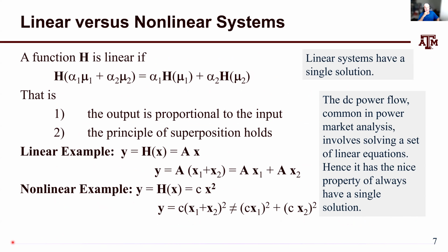Okay, we're going to be talking about nonlinear systems today. The power flow in its standard AC form is a nonlinear solution method. Linear systems are nice. Linear systems have the principle that the output is proportional to the input, and you can apply superposition to them. If you work in market analysis, you might be solving DC power flows. DC power flows have the very nice property that we are solving a linear system. And when you solve a linear system, you only have one solution. And as long as your A matrix is invertible, you're guaranteed that a solution exists. This is not the case with nonlinear problems, and the standard AC power flow is definitely nonlinear.